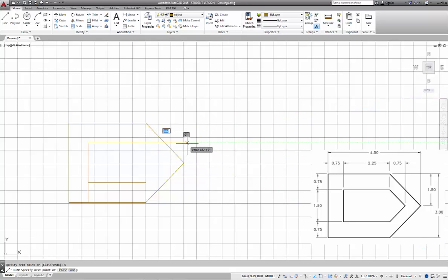Whew. That's what happens when you're not watching the screen and typing, is that you inadvertently move the mouse and you don't get a straight line. So I need to go 0.75 and then 0.75 down. And then we draw the hypotenuse back in. Remember, we look for the endpoint. There it is. Left mouse click, and then either the escape key on the keyboard or right mouse click cancel. Draw one more line from here and connect.